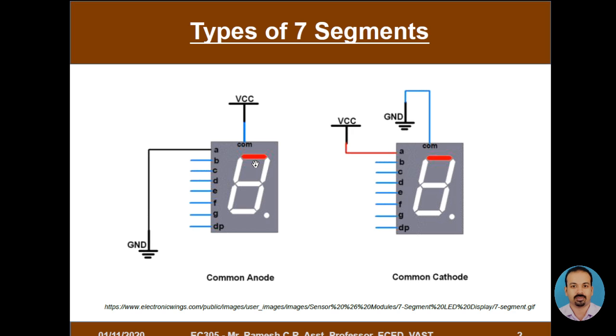If I need to implement 0, 1, 2, 3 etc., and even A, B, C, D, I will just focus on the 7 segments A to G. And if I need precision, for example to display 1.22 volts using this 7 segment, then I can go for the decimal point representation with this 8th segment, that is DP.